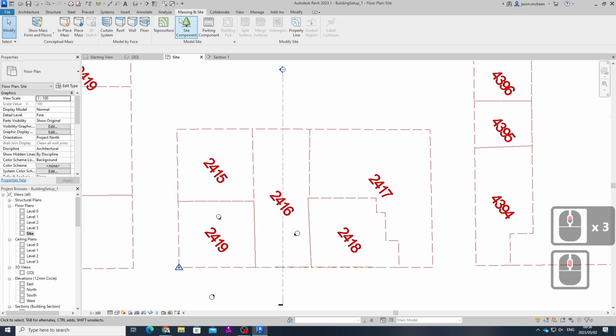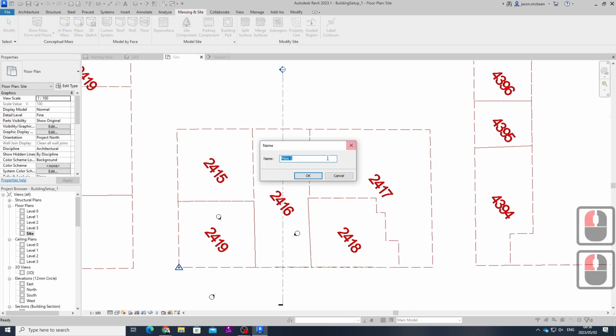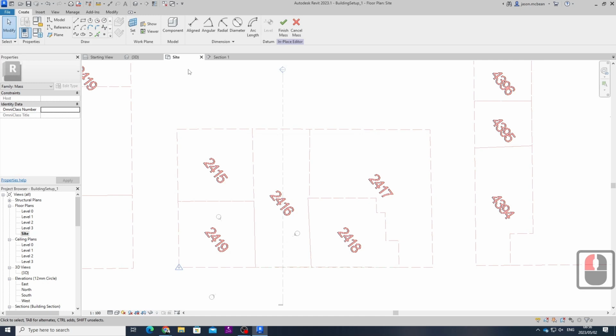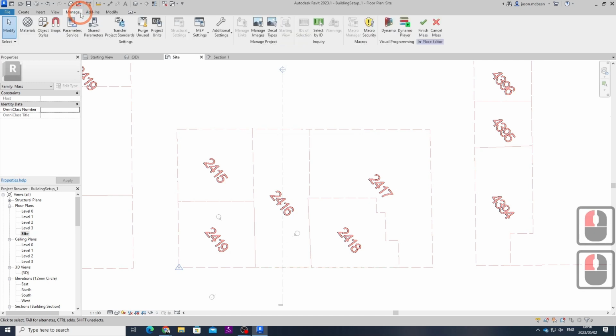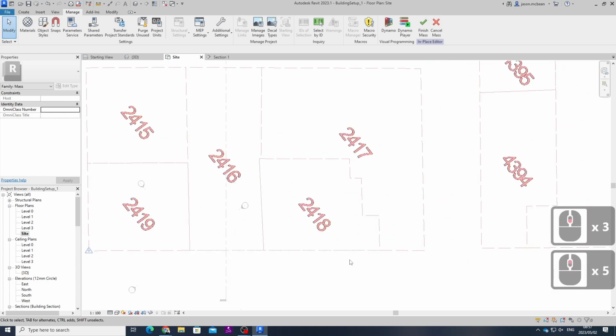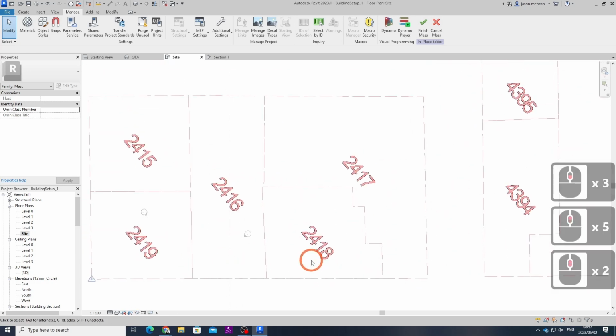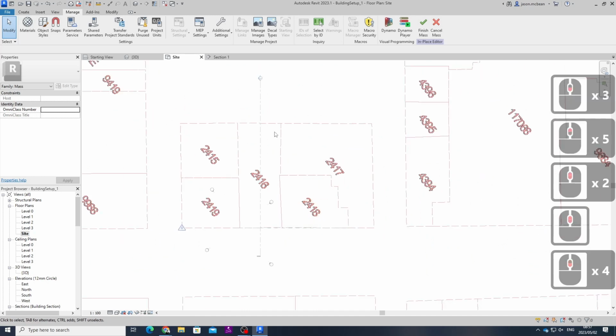Okay. So what happens is if you go to the massing tab and you go to model in place, you can give it a name. I'm just going to call it mass 1 for now. Okay, great. Now by default, masses don't show because they drive form. So I'm going to create something very organic in this space, and I'm going to show you how to model something very organic. Okay, so we'll start with something organic to show you that there is this possibility.